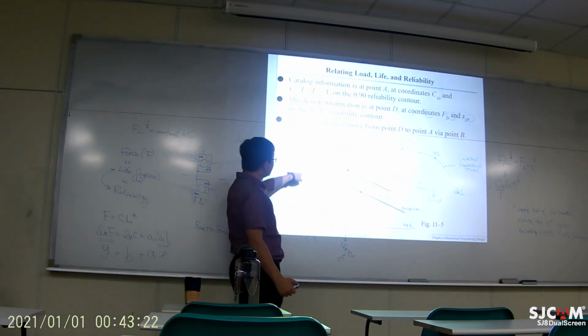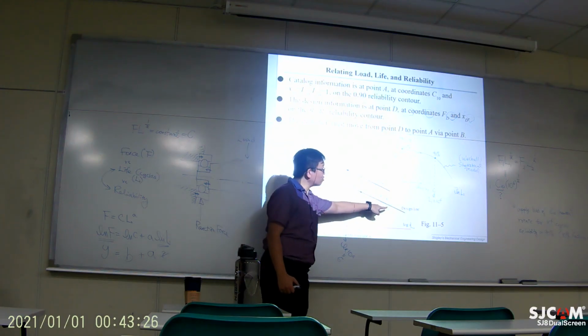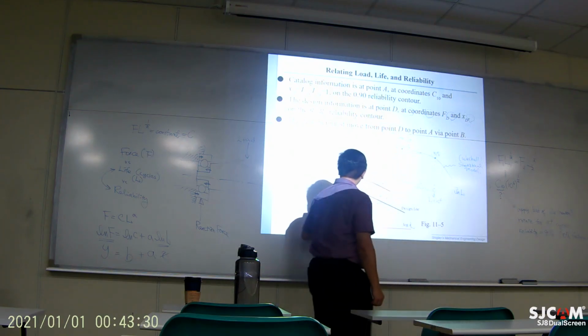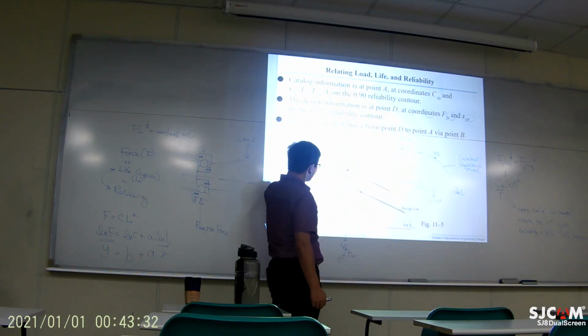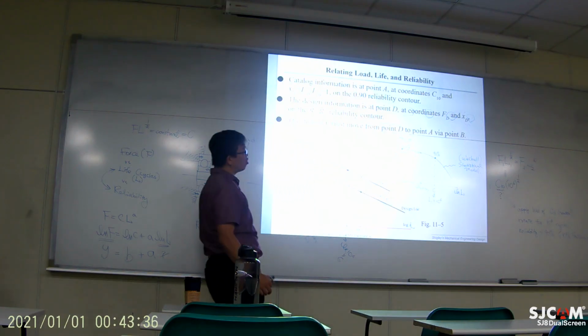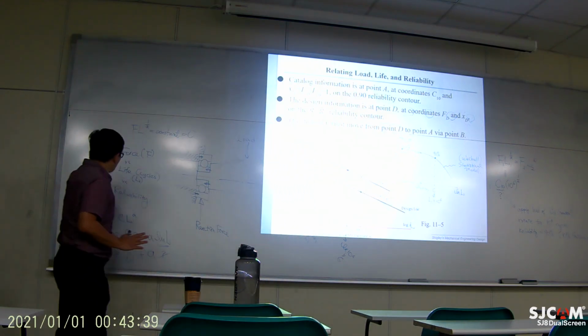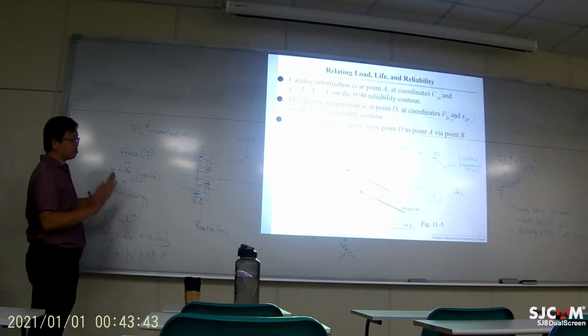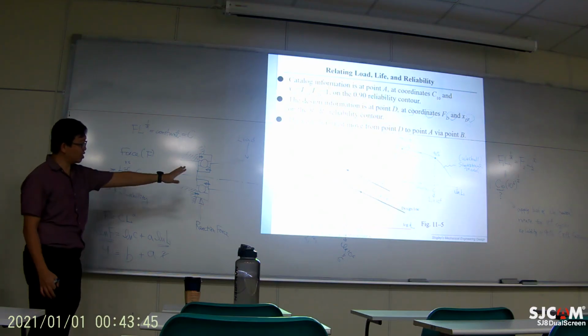And once you find this point, this line is valid. You can still use this linear relationship. You can use it to design for a specific point with specific reliability. So force, life, and reliability, all three are tightly related in this particular drawing.